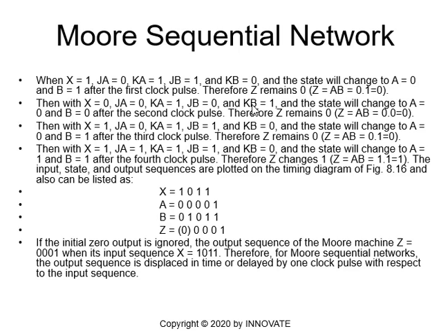Now, if you forget the mode of the JK flip-flop, use the next state equation, or we call it the characteristic equation, namely Q plus is equal to J Q prime or K prime Q. So if you use this general equation, you can find the next state easily as well.